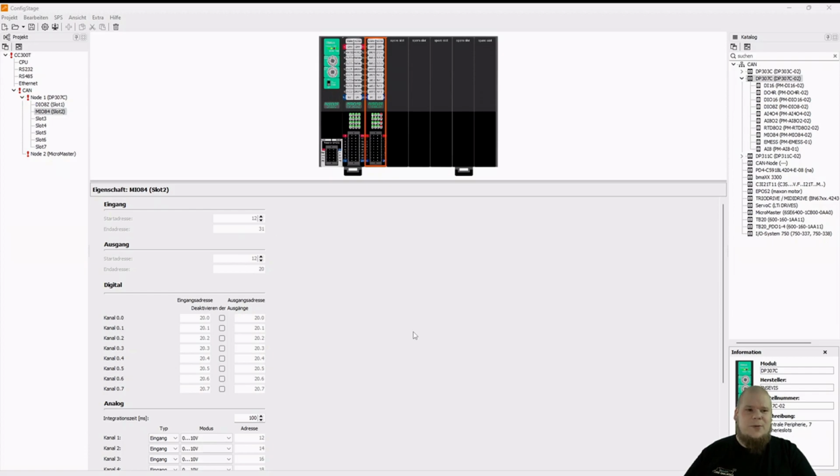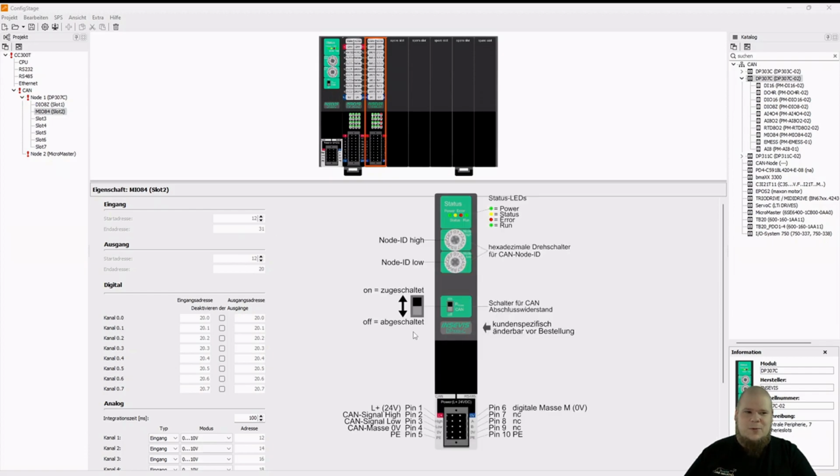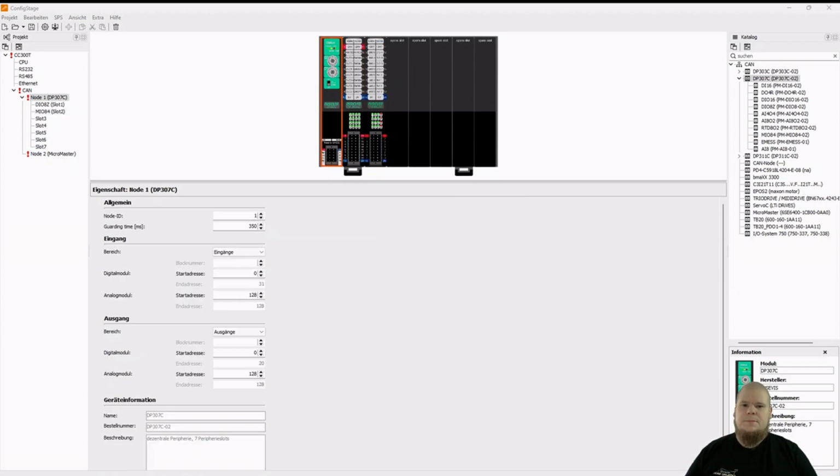The issue of bus termination. We have already had cases where the customers simply switched on the terminator resistor at each participant of the bus. Of course, the whole thing didn't work then. The bus termination is done at each of the two ends of the bus system. With very short bus lines, it may also be possible to terminate at only one device.